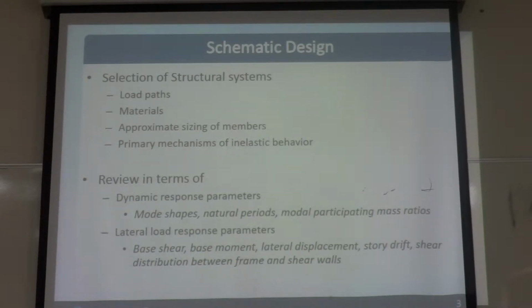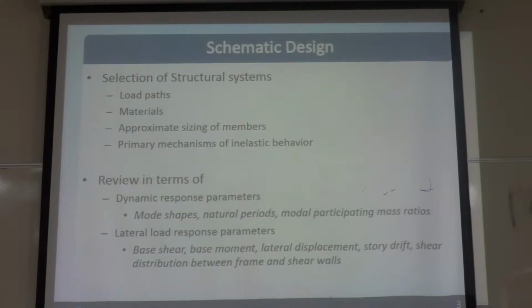Normally, story drift for tall buildings, for design level earthquake, we check the limit at 2% drift. Story drift means the relative displacement between two floors: the upper story displacement minus lower story displacement divided by the height of the story.